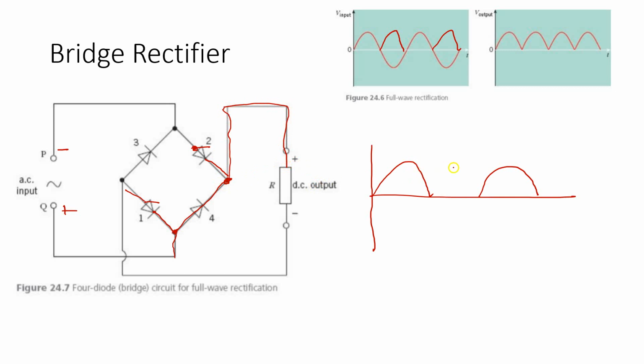So this is now when I take the negative portion and put it in between here. You understand? So that is when I get this type of thing that we call full wave rectification. So that negative wave that essentially was here, we're now taking it and flipping it and bringing it up at this point to rectify. Then this signal continues all the way. It comes back to this point. It jumps over the wire. It comes to this point back here to this node.